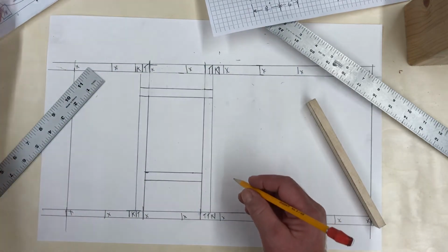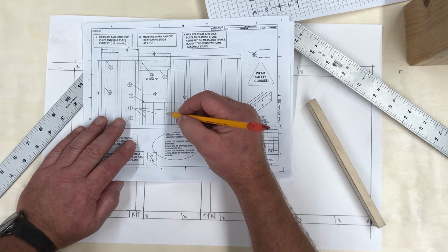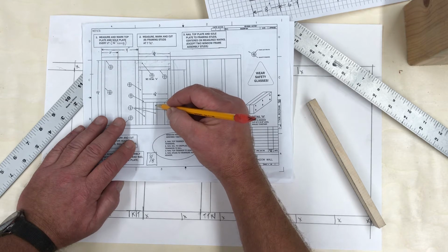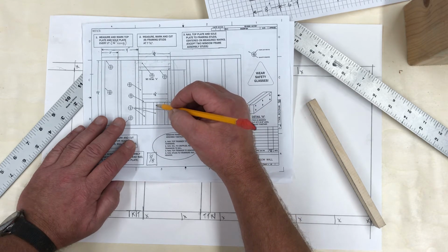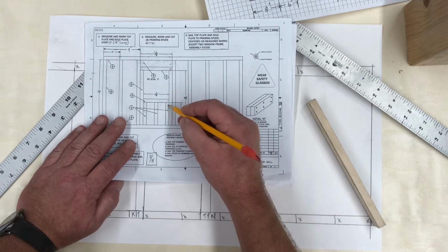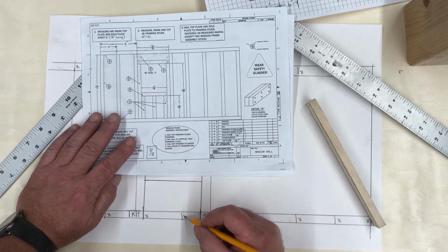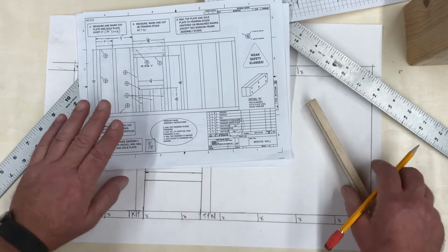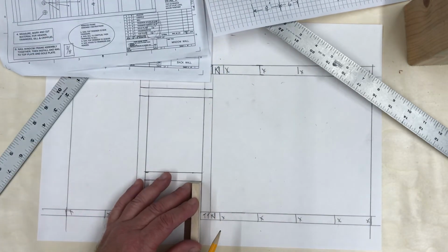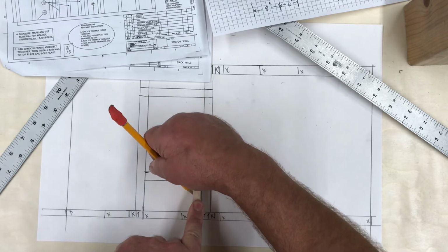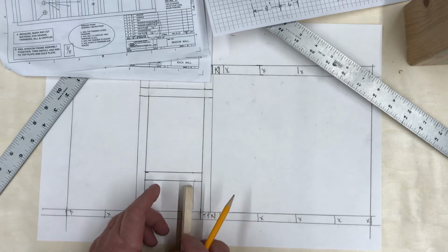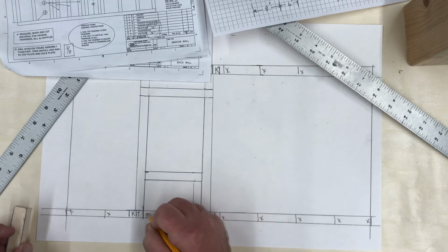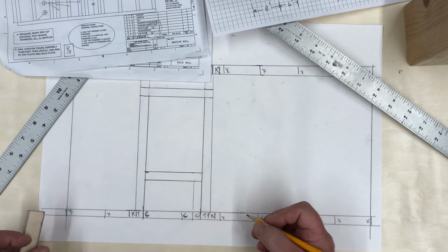Now, we also know that by looking at this packet, we have a cripple stud here and another one here. This one will vary according to your design. Some of you won't even have a third cripple stud. You will only have the ones on the ends that are required. I can tell by my design that I need an additional one here because these were the 16 inches on center. So I'm going to draw the cripple stud here. This turns to a cripple stud, and this one will become a cripple stud.